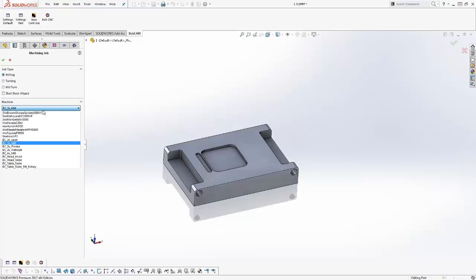Now, in most scenarios, the BC3X mill, if you're running a vertical machining center, is going to be just fine. If you're running a router, sometimes you have to do some adjustments because you may get inverted or mirrored letters. So you can do this stuff yourself, but generally just use the default machine. You don't need to rename the machine. You don't need to change the machine unless it requires you to do so because your toolpath isn't coming out right. But just by default, the BC3X is a great place to start.